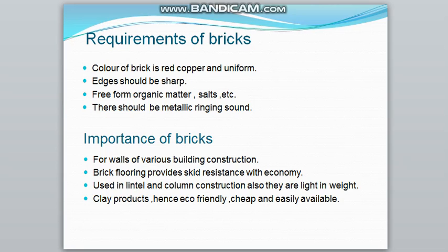Now we'll discuss the requirements of bricks. Generally, clay bricks have the most requirements. The color of the brick is generally red copper and uniform. The edges should be sharp, free from organic matter and remaining salts. There should be a metallic ringing sound.